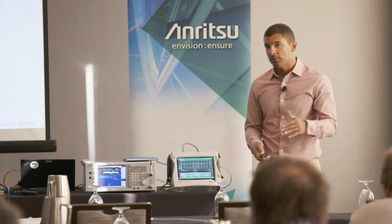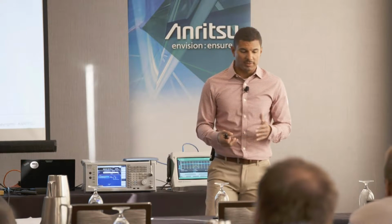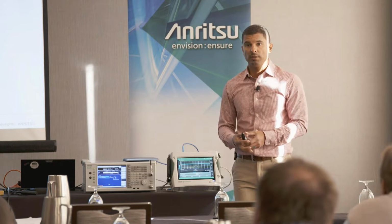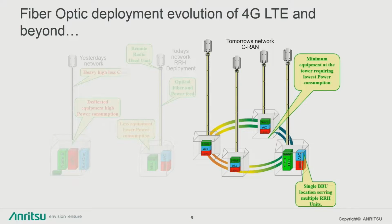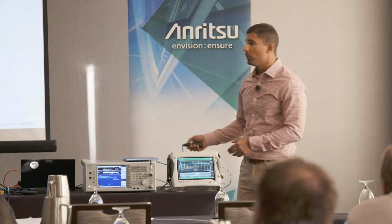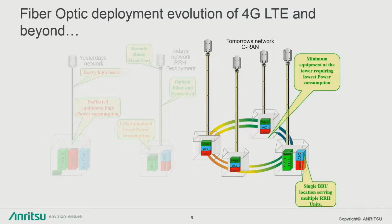All right? Now we move forward again to the third set. And what we've seen now is going from a DRAN, a distributed RAN, to that of a CRAN, which would be either centralized RAN or some call it cloud RAN. Now, instead of having just one dedicated BBU per radio head, we had multiple BBUs or BBU hotels, something of that nature, where you had multiple remote radio heads all feeding through a ring to a centralized unit.